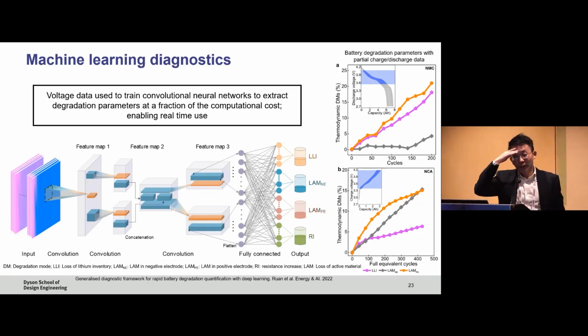Yeah, great question. So the challenge with some of these diagnostic techniques, if we're being completely honest, is that as your battery ages, they actually become less and less accurate. That lack of accuracy comes from heterogeneous degradation. If you think about a cylindrical cell, maybe in the center of the cell where it's hotter, you're going to get more degradation. And these models assume everything is lumped, so that starts to break down and the error increases.